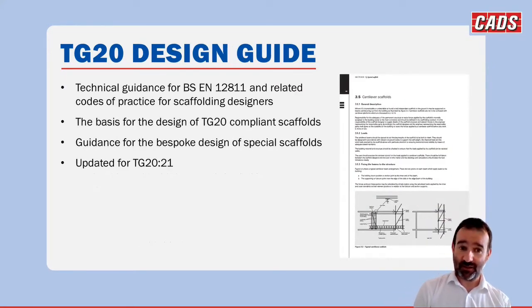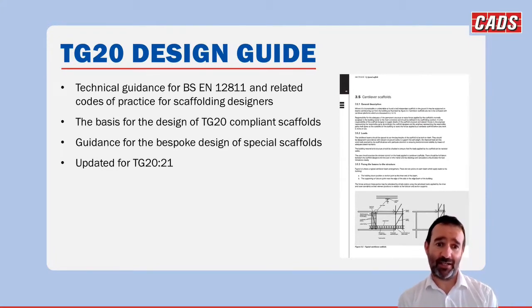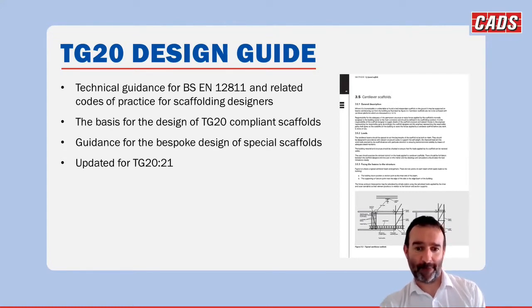TG20 also comes with a design guide. This is very much like the TG20 05 and 08 guide, based on 5973, but again, expanded and extended. And again, it covers two parts really. It gives the basis for design of the TG20 compliant scaffolds, so that it's not a black box and you can see how they were designed. But it also gives guidance for the bespoke design of special scaffolds that are not TG20 compliant. And again, we've updated this for the latest edition.